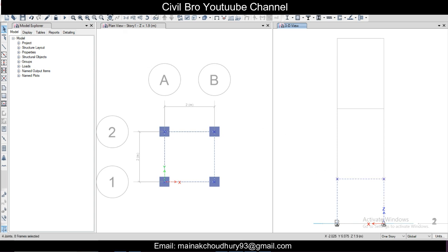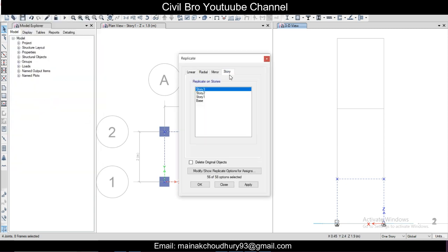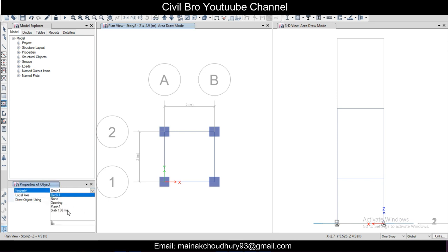Edit, replicate, and by story, the story 2, apply, and we'll go to story 2, move up to story 2, to the base, story 1 and story 2, and assign the slab. So for the slab, let's have here the option of quick draw floor, and just select this as slab 150 mm and assign the slab here.